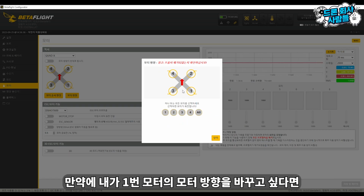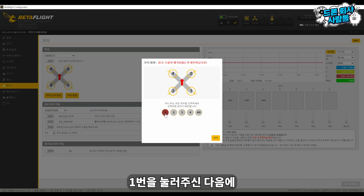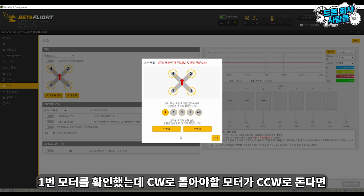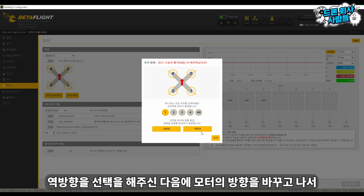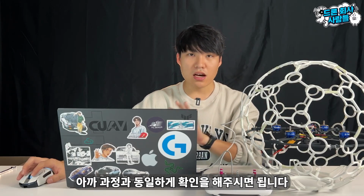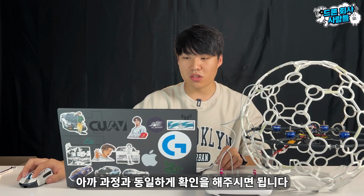If you want to change the direction of motor number 1, you can press number 1 here and choose whether to change it to forward or reverse. I checked motor number 1, and the motor that should rotate clockwise is rotating counterclockwise. Then, after selecting the reverse direction and changing the motor's direction, you can check if the motor's direction has really changed in the same way as before.